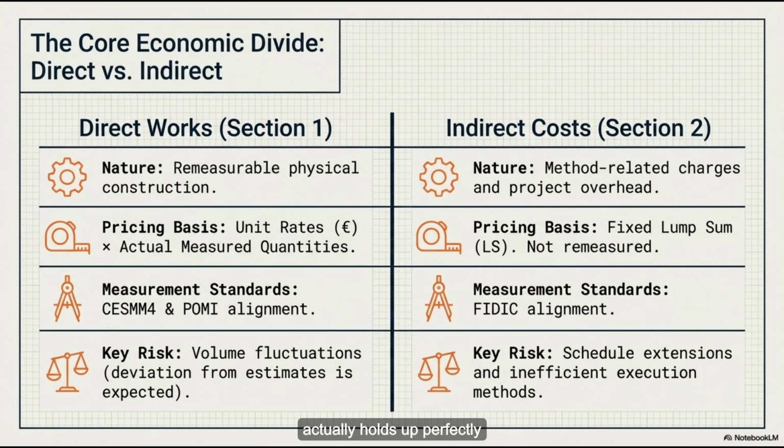Exactly. And that analogy actually holds up perfectly when we bring in the governing philosophies mentioned in the document. All the acronyms. Yes. The text explicitly notes that this schedule is prepared under the FIDIC Red Book conditions of contract. And for anyone who follows global infrastructure, FIDIC is essentially the bedrock of international construction law. It really is the gold standard. Yeah. The Red Book specifically designates a structure where the employer, so the client, handles the design, and the contractor executes it on a remeasurement basis.